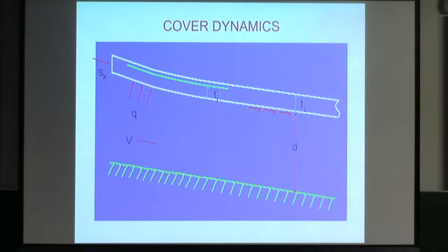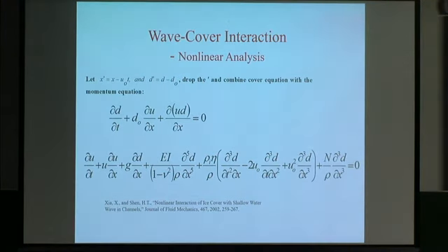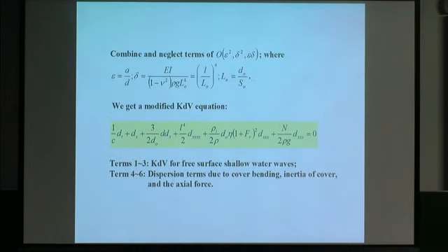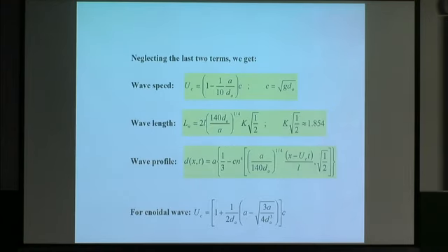So we said, and Steve started looking at the wave-ice cover interaction. So we followed that and considered both the mechanisms already mentioned, and tried to do some nonlinear analysis. When we combine the flow equation with the ice cover equation, an elastic plate, we get a nonlinear equation like this, and then we get a solution.